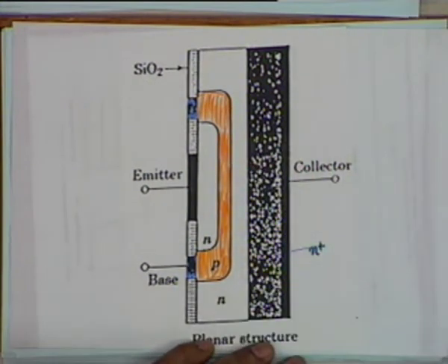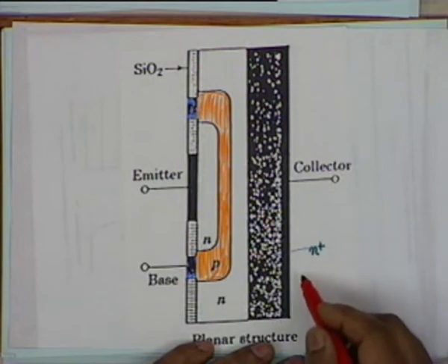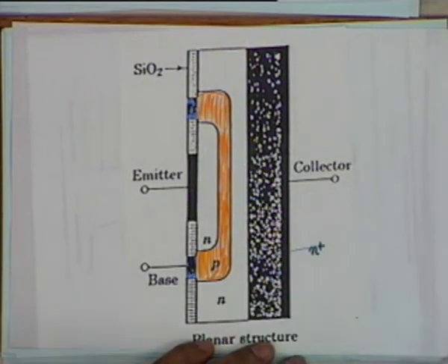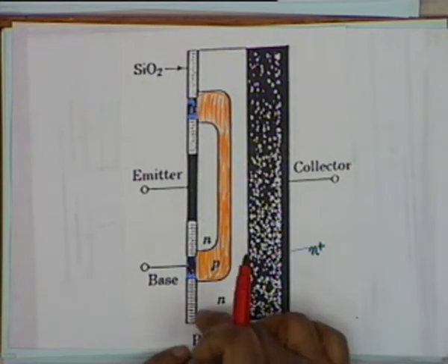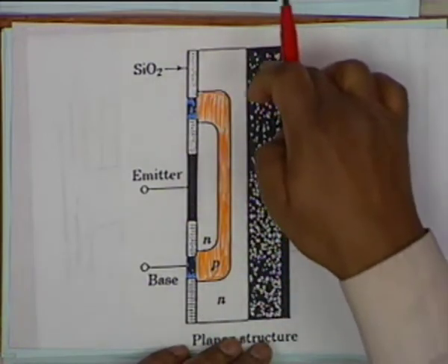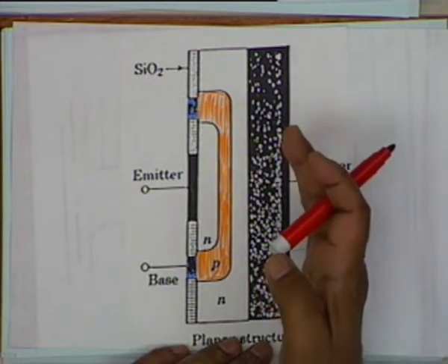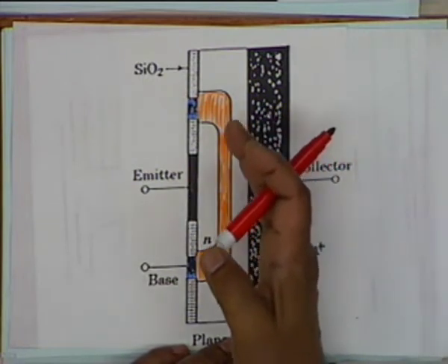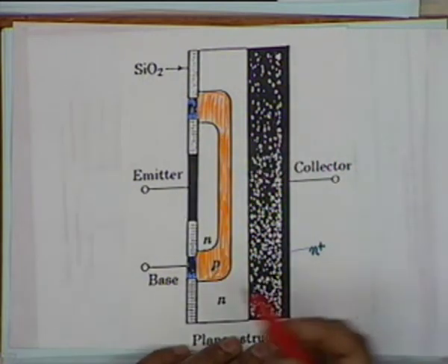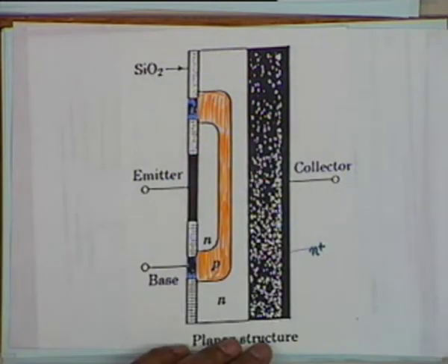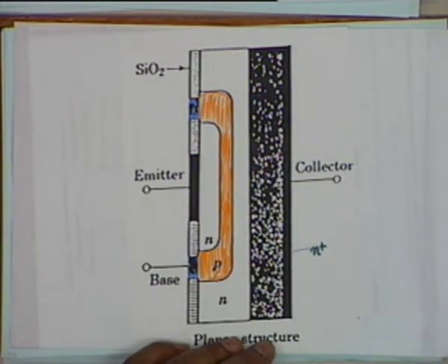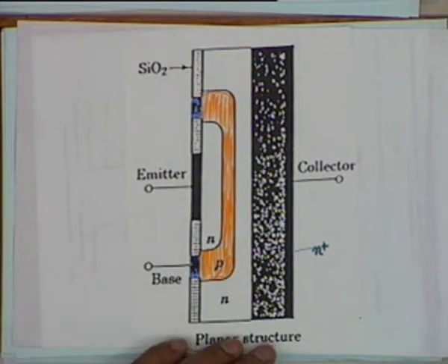This is why it is called a collector. So the collector is usually N plus and then a metal contact. Actually this whole region is collector, N plus and then the metal contact. The metal contact is between metal and N plus instead of N. It does not matter that much in the case of base and emitter, because very large currents will not have to be handled there.